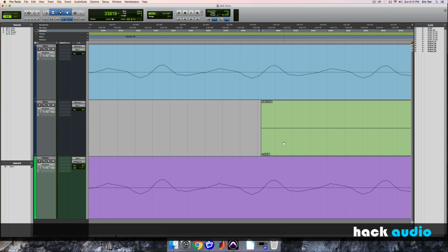Well, because we know that this echo signal is an identical repetition of our input signal, another thing that we could think about is that we're going to add sample number 44,100 here plus sample number 1 of our input signal in order to get our output at sample number 44,100.